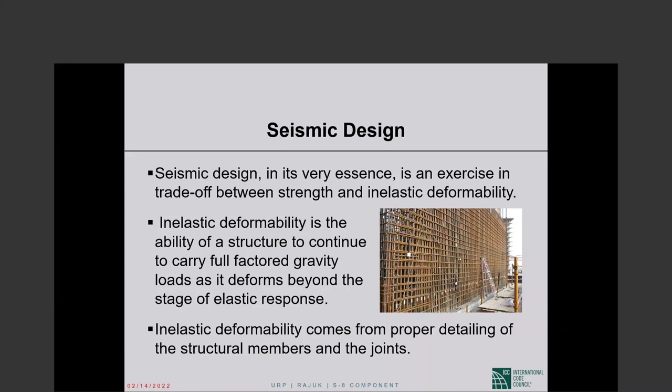And elastic, as I mentioned, does not necessarily mean stress proportional to strain. It means no residual displacement. The earthquake passes, you get your structure back intact and, very importantly, located where it used to be before the earthquake.